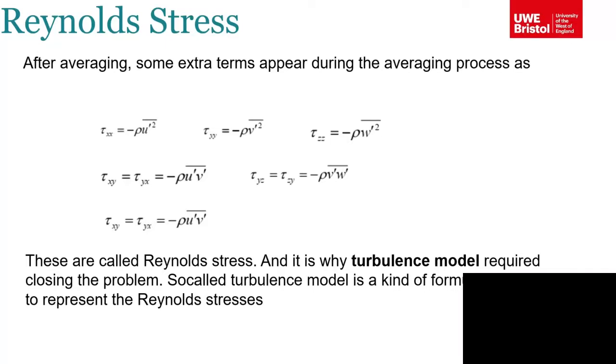When you write the Navier-Stokes equations for turbulent flow, you add those fluctuating components in the equation as well. Because you add those fluctuating components, those are new unknowns. Therefore you need to have an approximation for those unknowns as well. That approximation is called turbulence modeling.